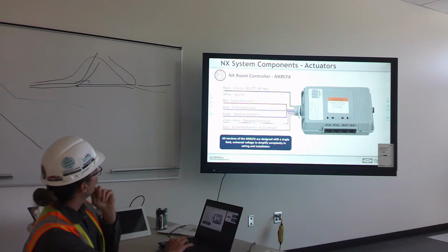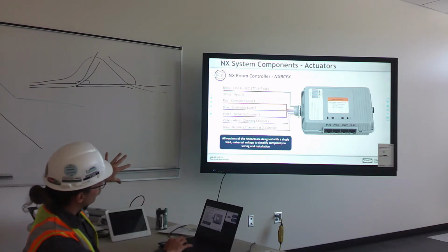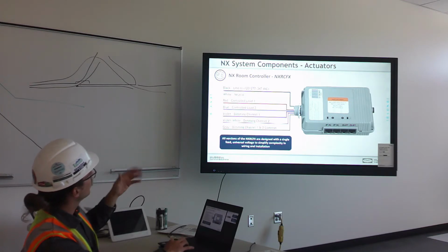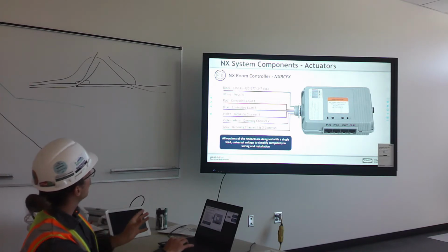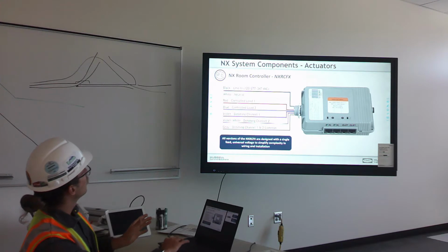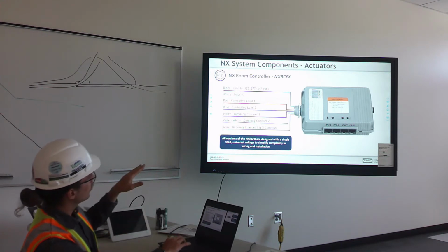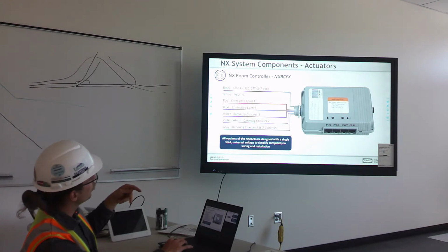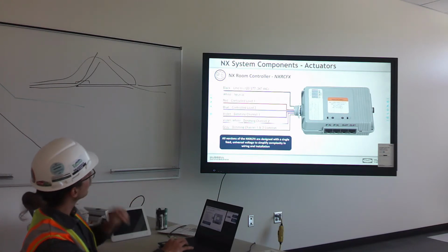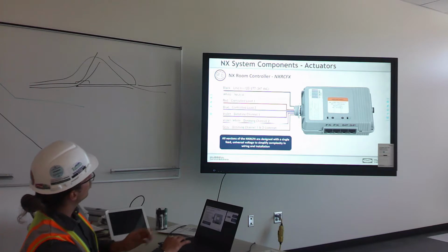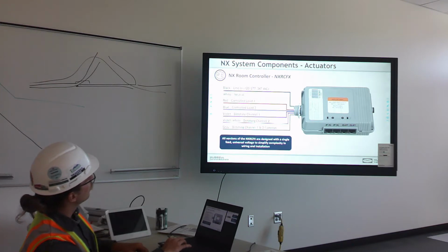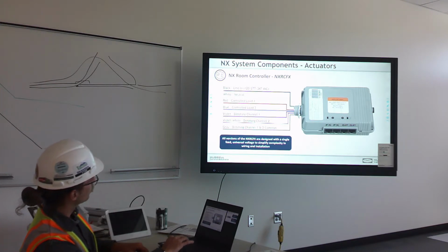So over here, we've got the diagram of all the wires you'll see coming out on the line voltage side of the controller. So you've got your black, which is your line in, neutral for white. Red is your switch leg for relay 1. And then if you have a second relay in the controller, blue will be number 2. And then your 2 dimming outputs for a 2 RD controller. And then your common for both dimming outputs.